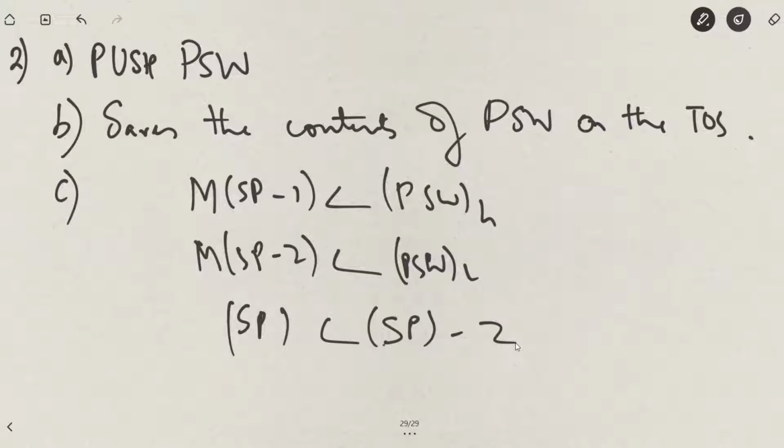So the process status word is a register pair. It is formed by the accumulator and the flag register. We actually could have combined this with push RP, but somehow this has been clubbed separately. So everything else will be the same. It will be a single byte instruction. It will have 3 machine cycles. It will have 12 T states. It will have an execution time of 3.84 microseconds. Whatever was for push RP. Now there will be no variation because this is the only variation that exists for itself, and no flag register will be affected.